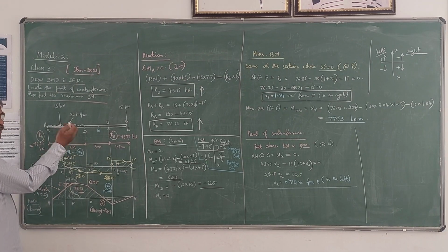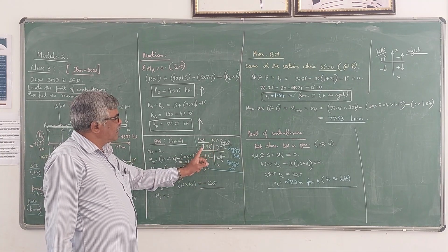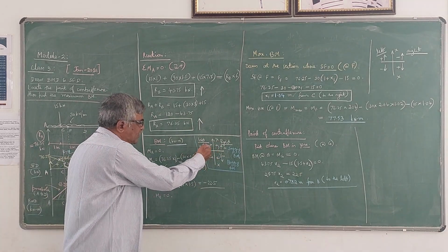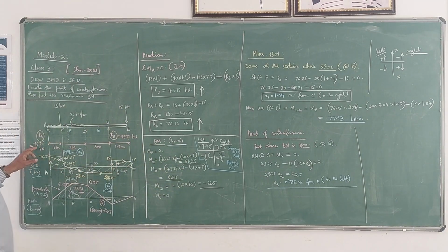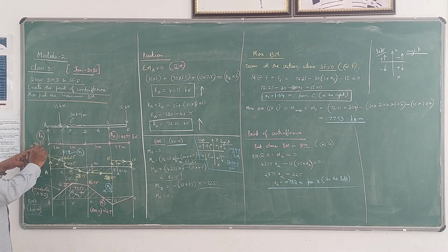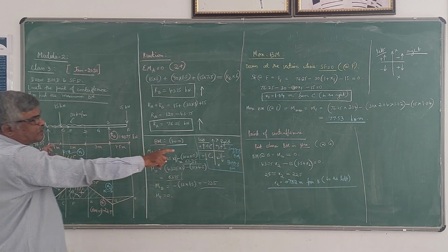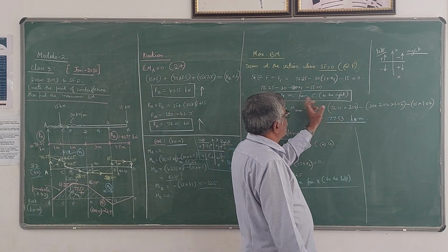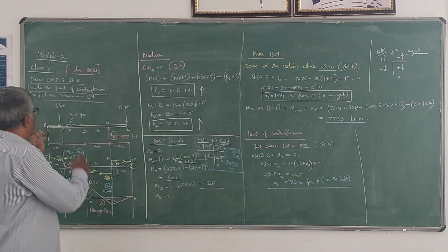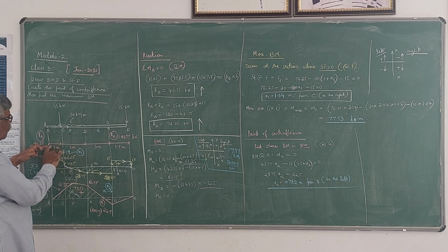Now at the same point F, you calculate the bending moment. For calculating bending moment, this is the sign convention you have to use. On the left side, upward forces give positive bending moment, or sagging, and it will be like this. Downward forces give negative bending moment, hogging, and it will be like this. Now, looking at the left side of F, the bending moment due to this 76.25 kN is 76.25 into (1 plus x1). Substituting x1 as 1.04, 1 plus x1 means 2.04. It is upwards, therefore positive. Then this UDL is acting downwards, so the bending moment is negative.